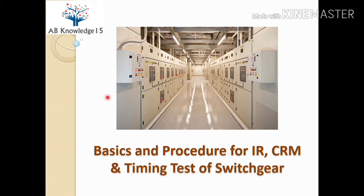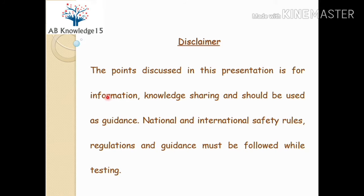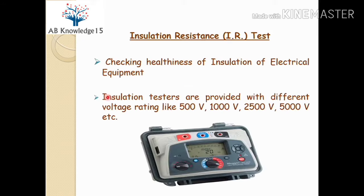In this video we will discuss three important tests of switchgear. The first one will be IR, insulation resistance. The second one will be CRM, contact resistance measurement, and the third one will be the timing test of switchgear. So let's start with the insulation resistance test.